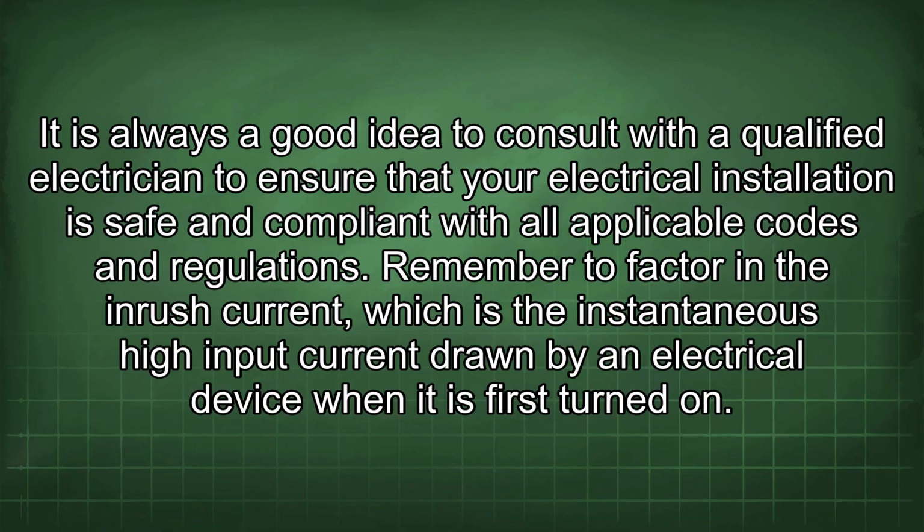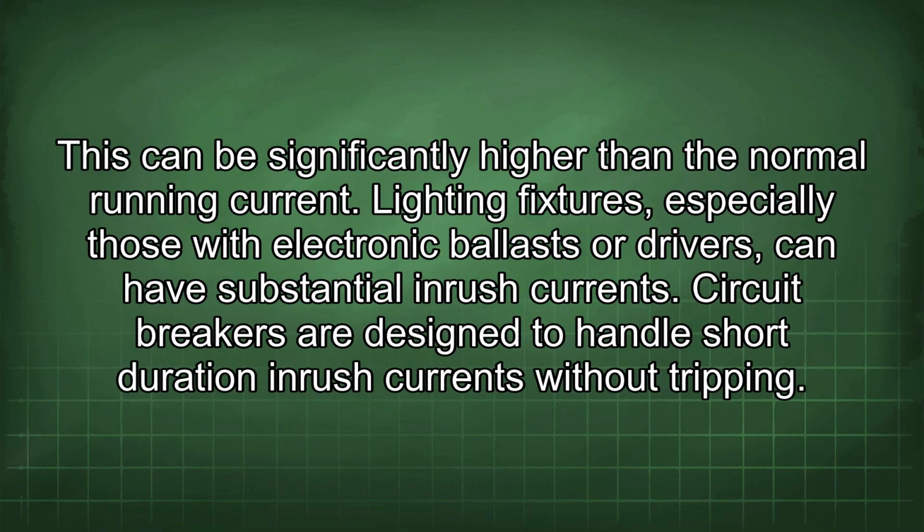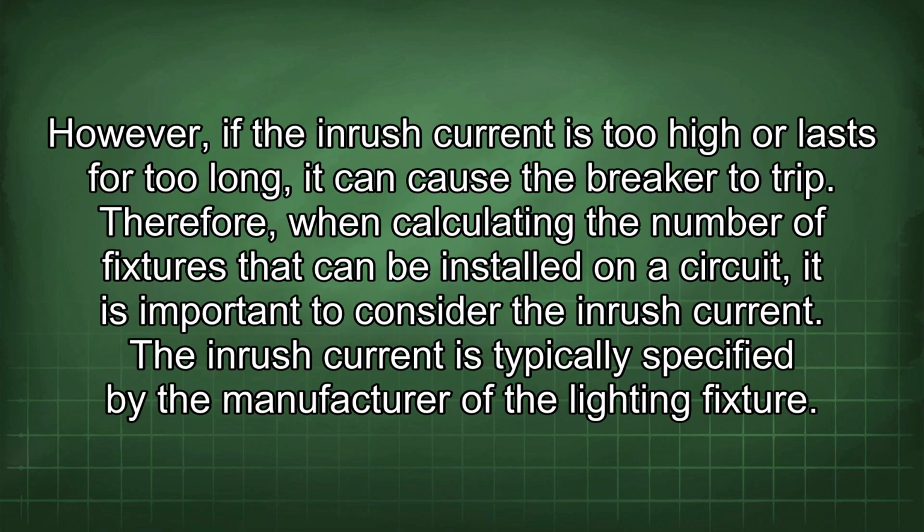Remember to factor in the inrush current, which is the instantaneous high input current drawn by an electrical device when it is first turned on. This can be significantly higher than the normal running current. Lighting fixtures, especially those with electronic ballasts or drivers, can have substantial inrush currents. Circuit breakers are designed to handle short-duration inrush currents without tripping. However, if the inrush current is too high or lasts for too long, it can cause the breaker to trip.